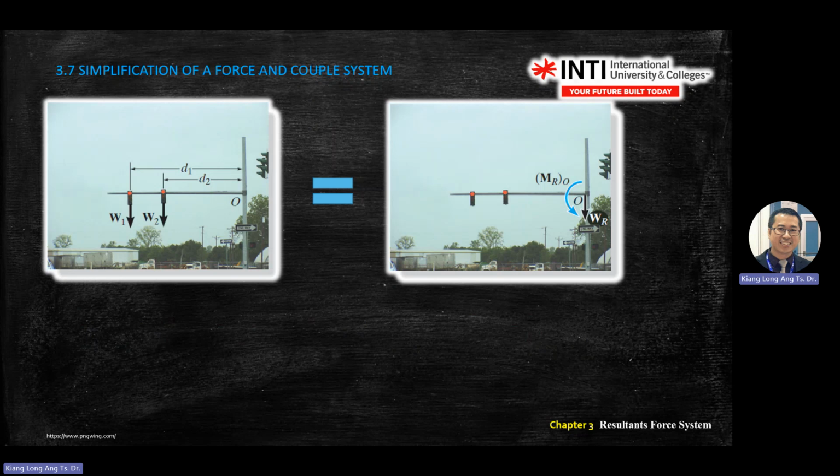And then you have here, when you transfer these forces to this point, remember it generates moment when you move these two. When you move forces by a perpendicular distance, the forces are still there. That's why you see there's a WR there. WR, because you combine the two forces, you move from one location to a new location, the forces will generate a moment, carried together with its own force magnitude and direction. Then it will generate a resultant moment there.